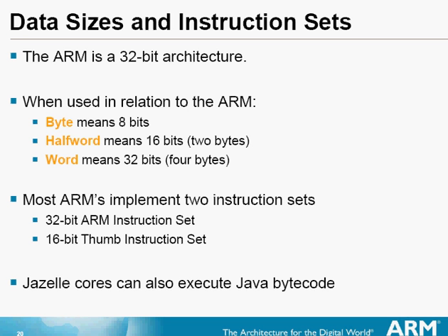Java bytecodes are 8-bit instructions designed to be architecture independent. Jazelle transparently executes most bytecode in hardware and the rest in highly optimized ARM code. This is due to a trade-off between hardware complexity, power consumption, silicon area and speed.